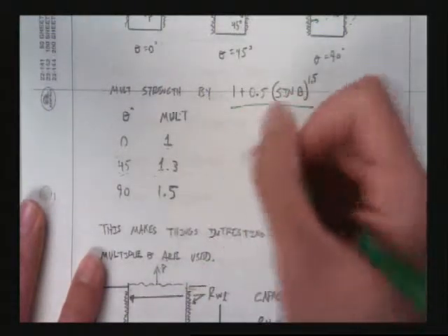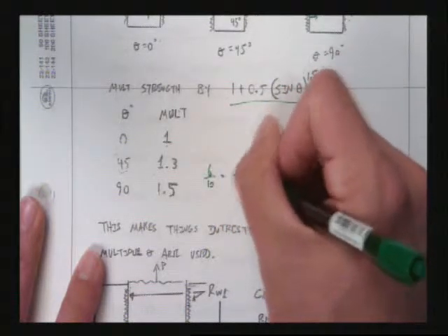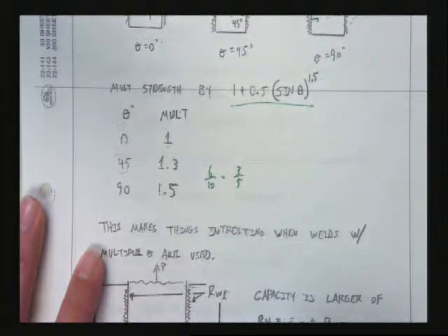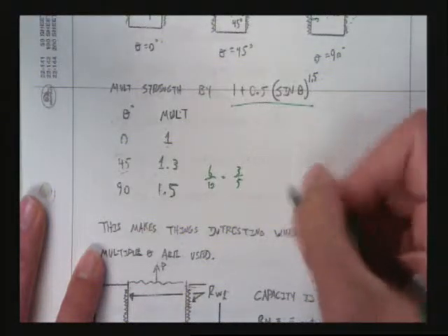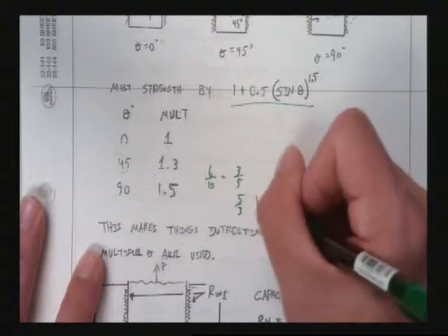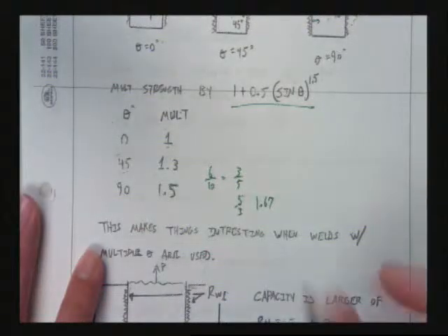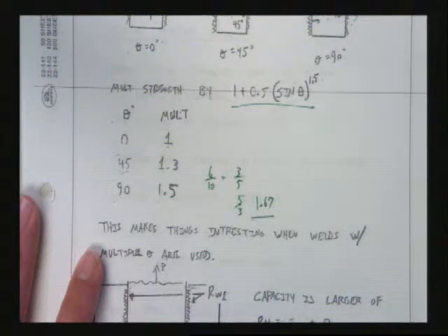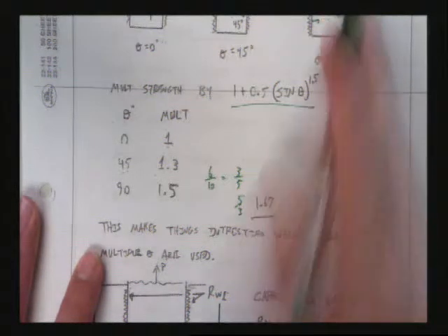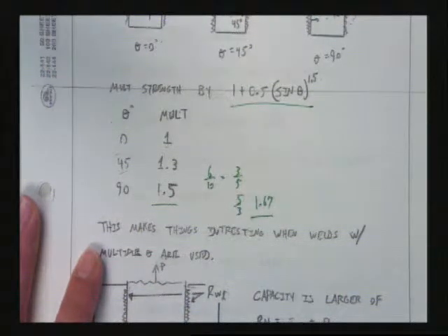Well, if I have 6/10, which is the same thing as 3/5, and I invert that, it's 5/3, which is like 1.67-ish. So 1.67 is what you should strictly be able to get if the welds were purely in tension and that was a pure, straight change of that 0.6. They're a little bit conservative here at 1.5. You with me? Okay, well that's what they do.